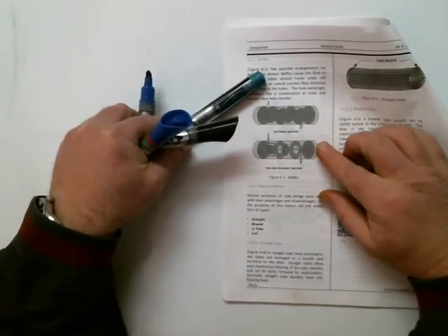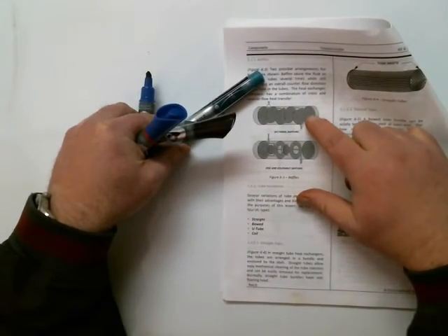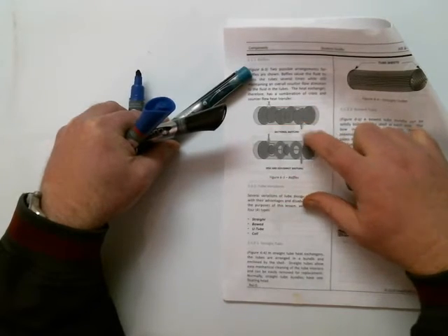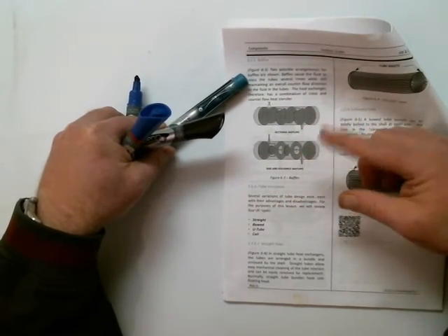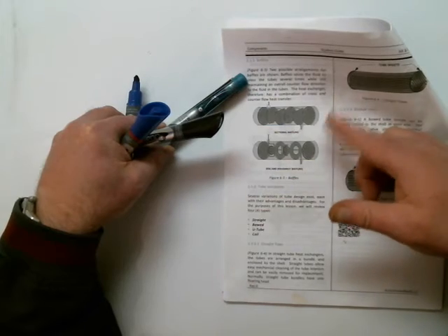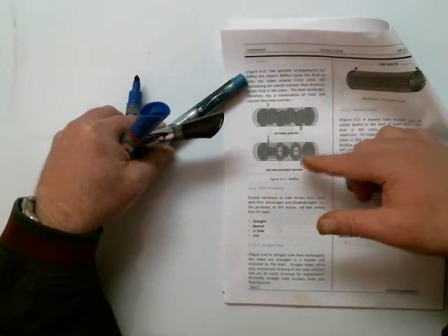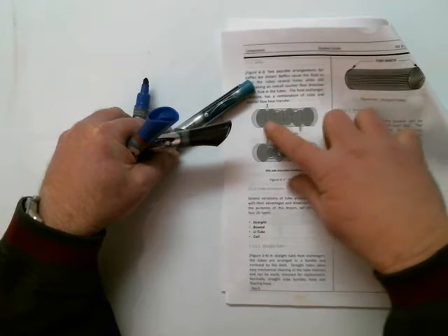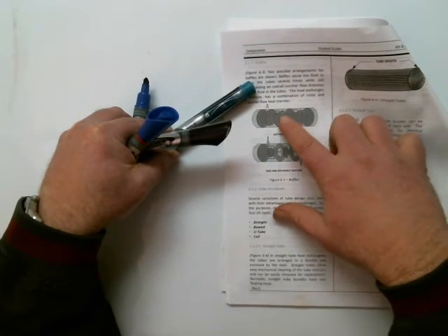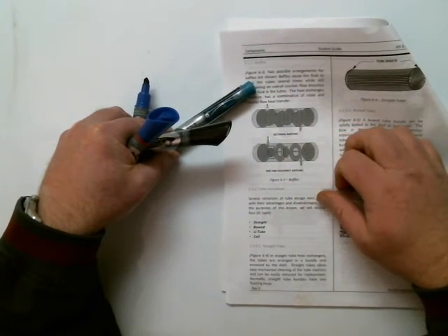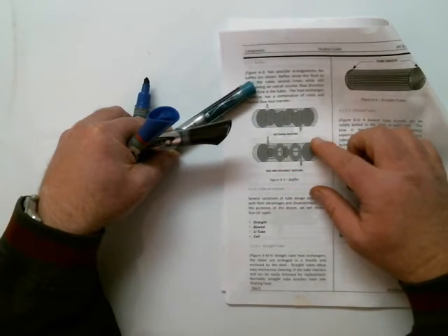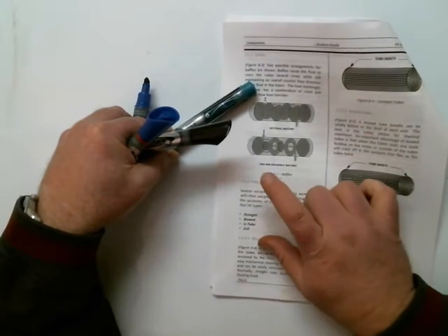So let's turn the page. And we do that, if you'll look, let this focus for a minute. There we go. We put these things called baffles in there. The baffles are arranged to cause all kinds of directional changes in the fluid, so that you get a combination of cross flow and counter flow and lots of good contact from the shell side fluid to the tube side fluid.